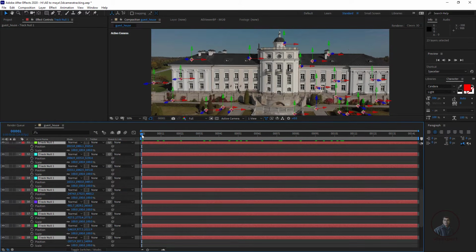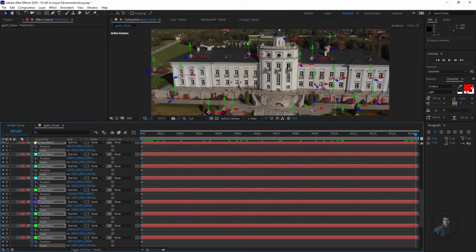So first this is the starting frame, so I played it at this starting frame here. Now we can simply create a key, so you can see. For both parameters we have to create a key, then go to the last frame, then again simply create a key. So this is actually the add key option. Okay, so here we have to click only the first time, then after this we can click on this add key option here.